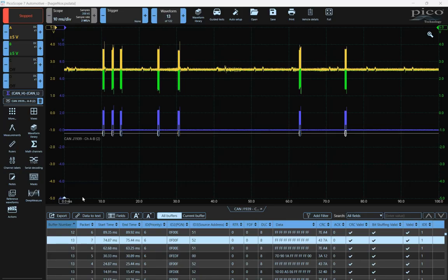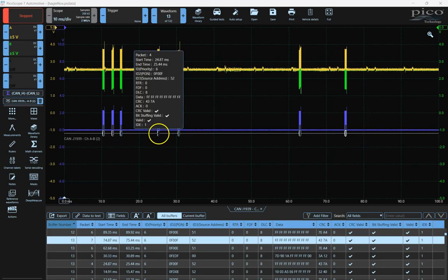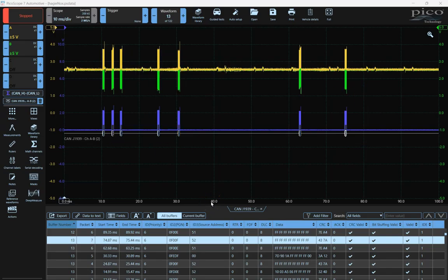So the NOx sensors, the engine control unit is going to request those or watch those, get that information from the NOx sensors they're broadcasting, or it may request specific information from the NOx sensors. That information would be broadcast much more frequently. So here you can see this is a tenth of a second in time. And so here I have both NOx sensors communicating more than one time within that tenth of a second.